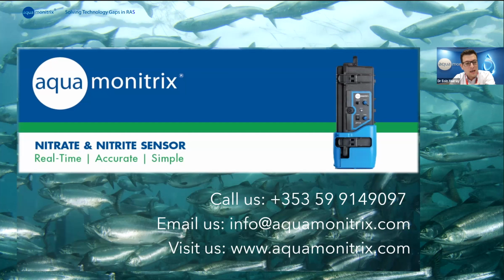Across all applications, the typical sampling frequency where most customers end up is every hour. At the start, sometimes we can be very eager to deliver every 10 minutes, every 15 minutes. But what we found is in general, macro trends are typically captured within 1 hour. We have some unique applications, especially around wastewater and aeration tanks, where they need 15 minutes, but typically for most applications, 1 hour is appropriate in terms of sampling frequency.